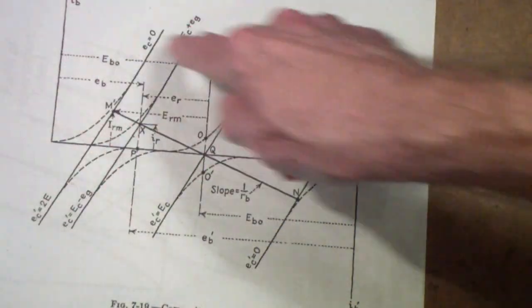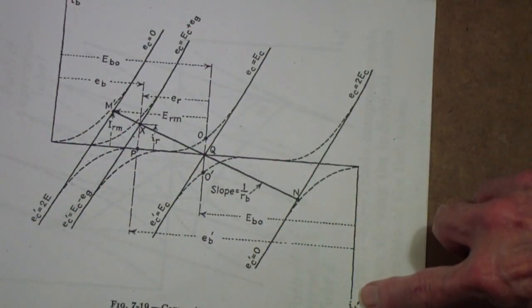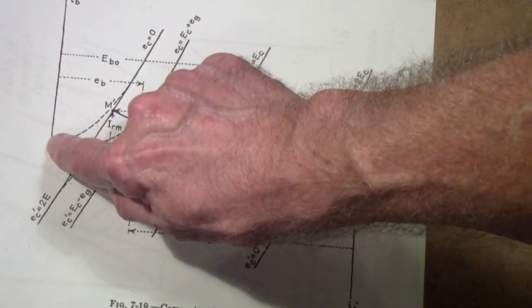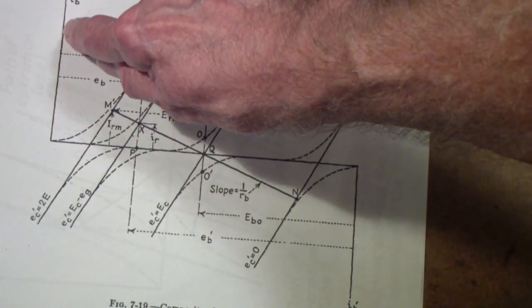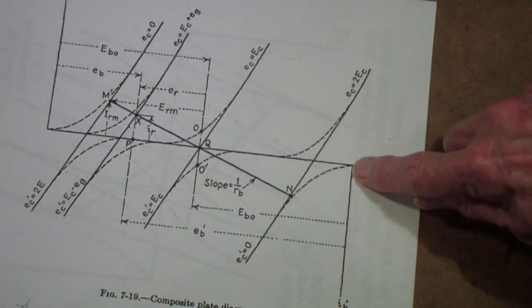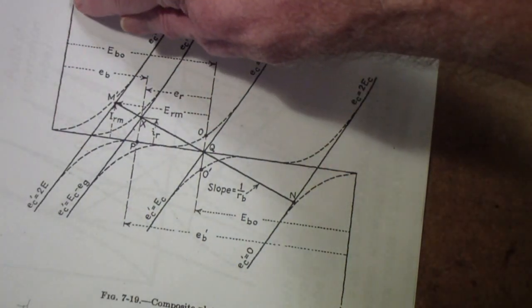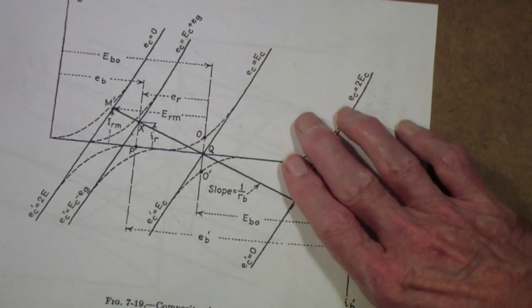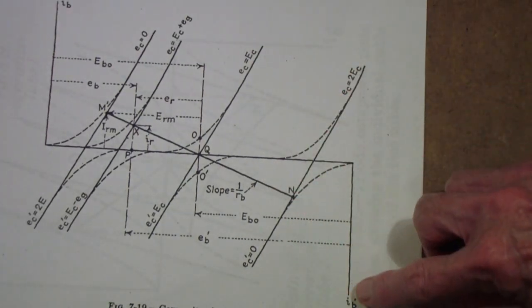And of course, this is plate current in one tube, and this is plate current in the other tube. Notice that when the plate current is going positive, or increasing, in this tube, it is decreasing in this one. Vice versa, as this one starts to come down, the plate current in the other tube starts to go up.